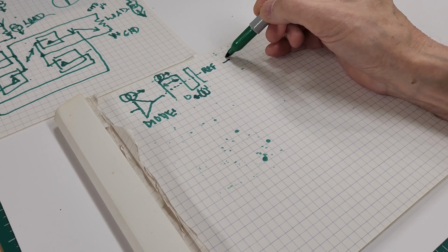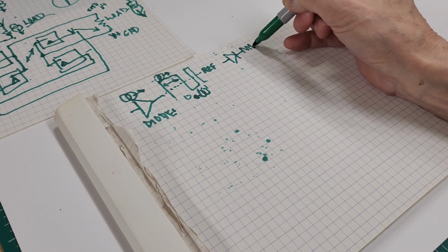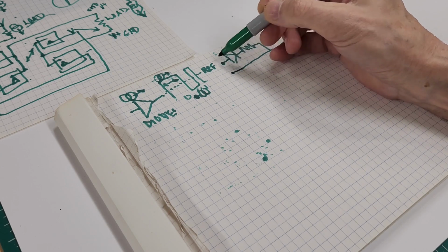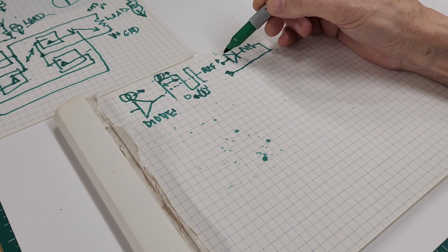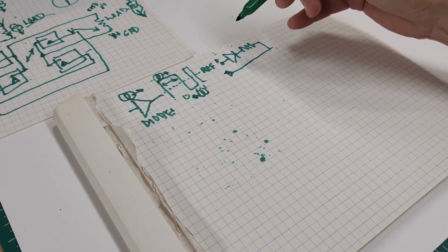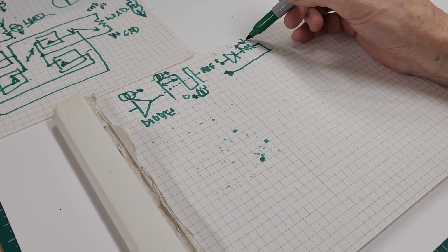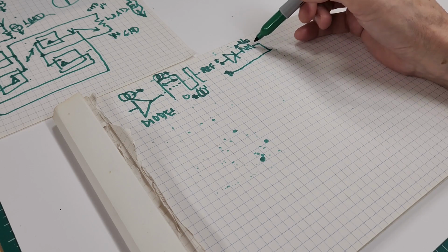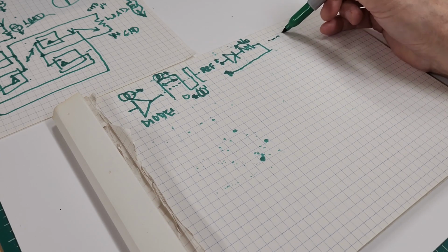So if we did a circuit somewhat like this with, say, a resistor, or what we just call the load, where the signal is being applied from the track, from the rails, across this diode, then the signal coming out of this, the signal actually being detected by the decoder here as a voltage, we'll just call it V naught, across the resistor, is looking like the top half of this signal.